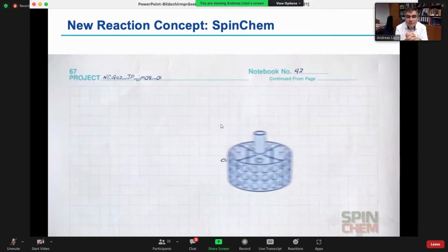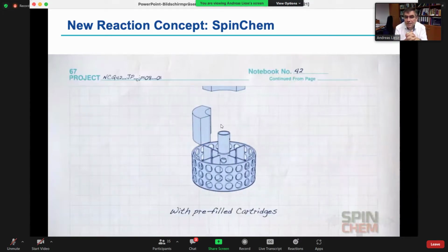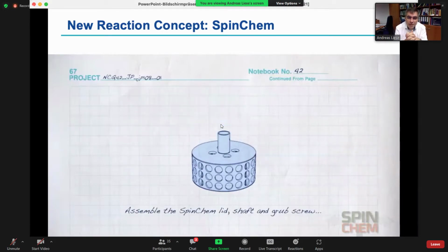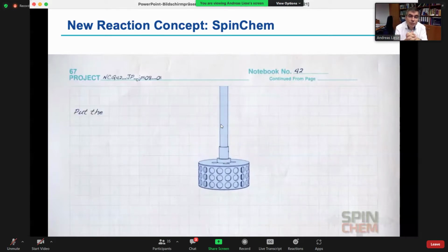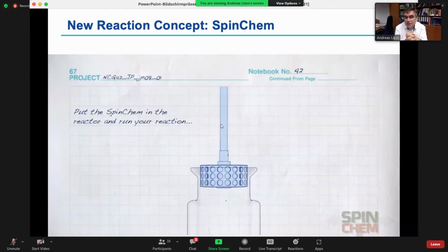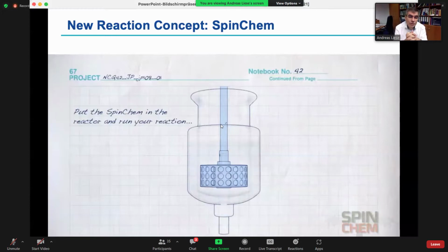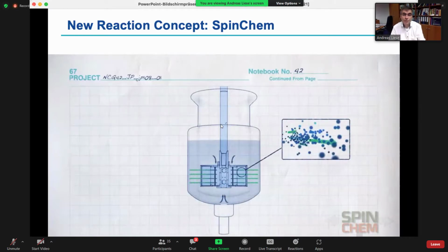Then we get in a stir tank reactor, if we're replacing the stirrer with this device, a convective flow through a packed bed, which demonstrates, if we operate it continuously, a CSTR operation in contrast to a fixed bed, which is plug flow configuration. Yeah, and that would be the setup. And here once again, see the convective flow in the particles.